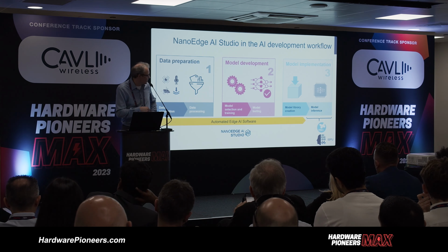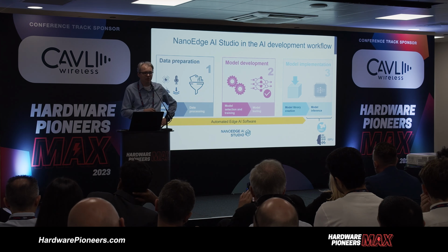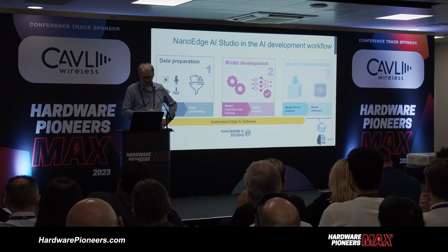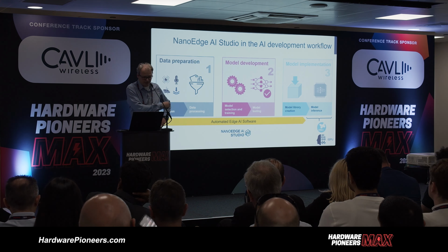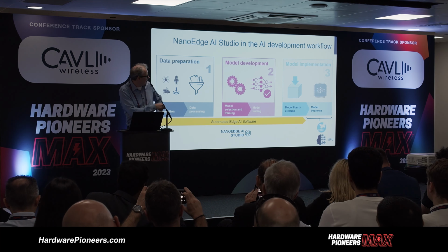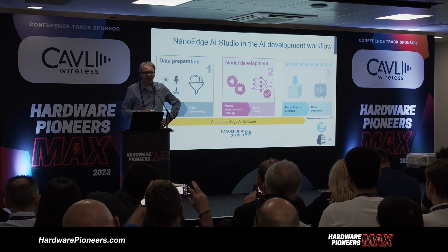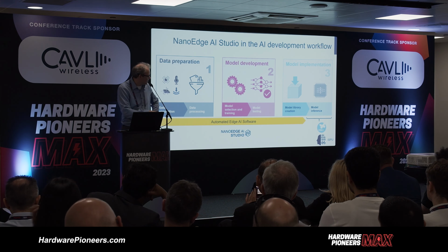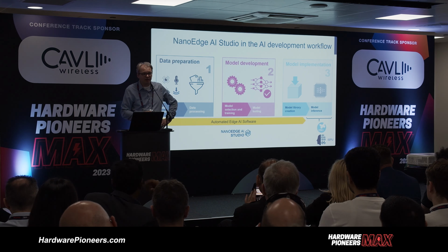Then it will select the best matching model for your exact use case based on the data that you have collected. And then you can test this within the tool itself, and then create a library in this last step in here, and then insert that AI algorithm into your STM32 microcontroller, or into the ISPU component, which is a sensor having a dedicated core to run these types of algorithms.